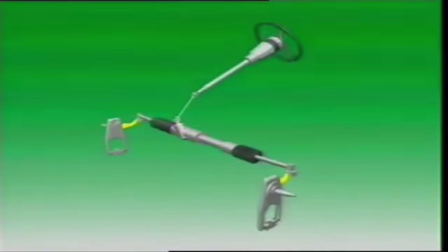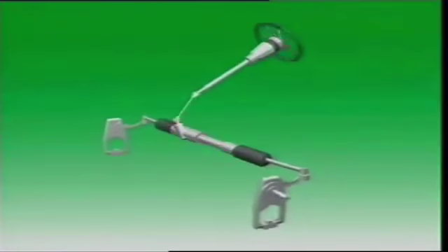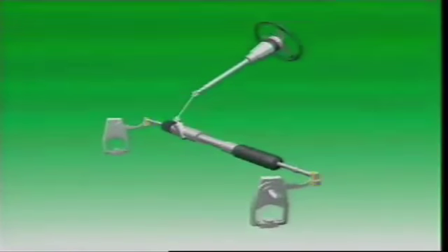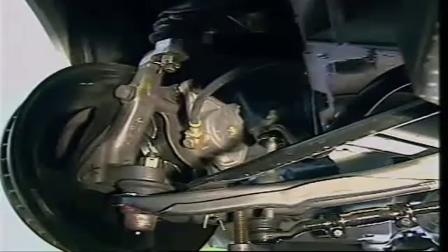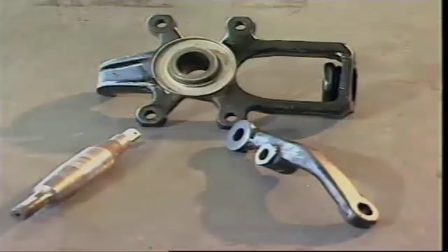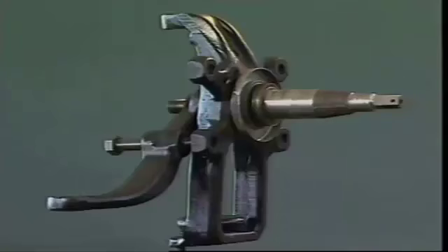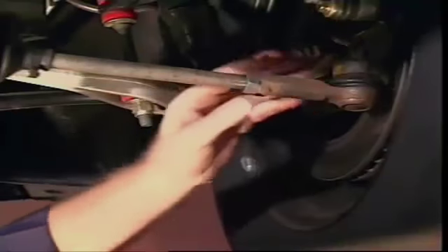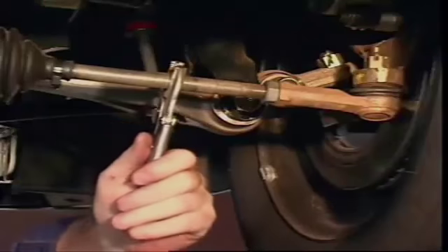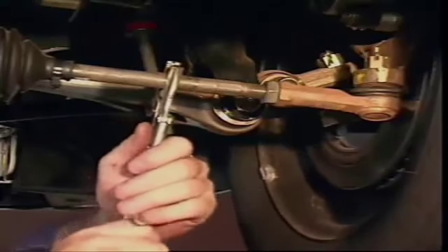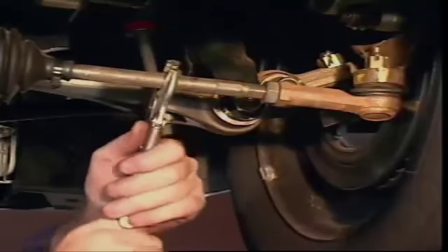The steering lever or steering arm is linked to the tie rod or track rod by a flexible ball joint that allows for suspension movement and steering rotation. The lever, the stub axle, and the stub axle carrier can be forged as one piece and can be referred to as a knuckle. They can also be made as separate units and assembled to form one piece. Each steering system makes provision for adjustment of the linkage to achieve the manufacturer's recommended tow setting. The track rods or tie rod ends are threaded to provide for their lengthening or shortening.